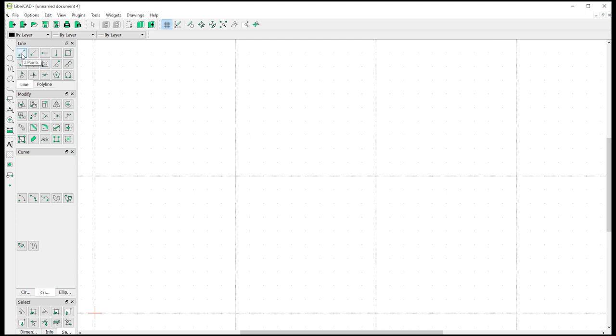And we've got some simple controls over here for drawing lines and what have you. So I can left click to start a line, left click to finish a line. This is exactly the same as I was showing you in the last episode. We can draw a horizontal line. In this case, I've chosen the horizontal tool, and up here we can type a length in. So let's make my line 100 millimeters long, and there we go, we've got our 100 millimeter long line, and it's attached onto that point there because that's where I dropped it.